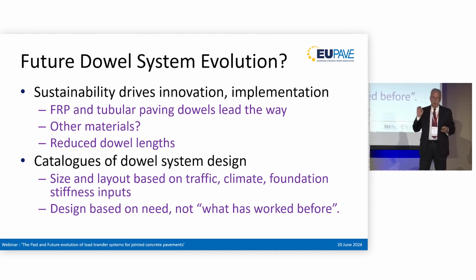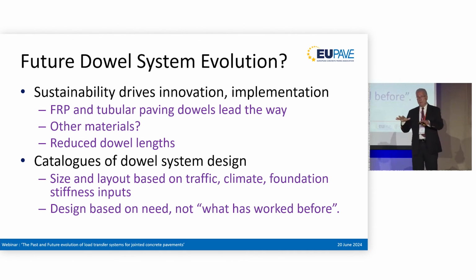So design based on what we actually need for any given project, recognizing that different levels of traffic, different weights of traffic, different climates, different foundation stiffnesses, all affect the amount of load going into the dowel bar, and the dowel bar system should be designed accordingly.